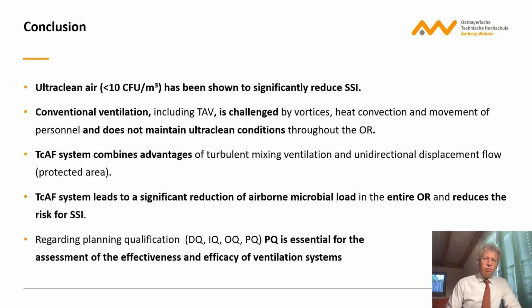So let me conclude. It has been clearly shown by numerous studies that ultra-clean air, meaning less than 10 colony-forming units, significantly reduces surgical site infections. Conventional ventilation, including laminar airflow, is challenged by vortices, heat convection, and movement of personnel, and does not maintain ultra-clean conditions throughout the OR.